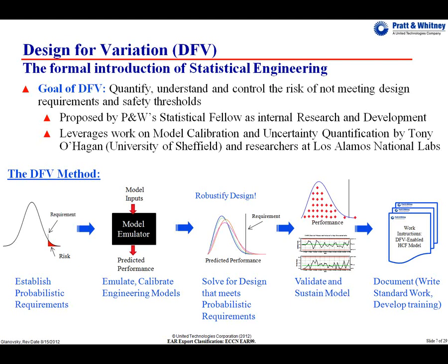We statisticians know that there's very few real-world situations where you have a 0 probability of exceeding your requirements and getting something to fail. The whole point is trying to get the probability of exceeding those requirements to be as small as possible. Once we get our models to start thinking in that way, we can really quantify, based on the percent of fallout, the percent of bad parts, what designs are better than what other designs.